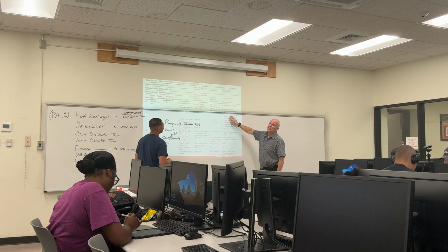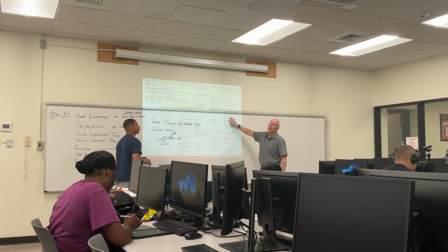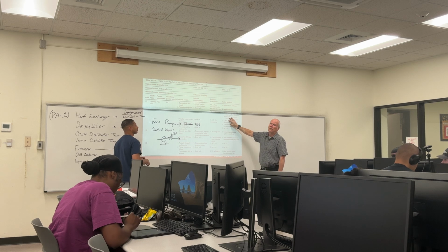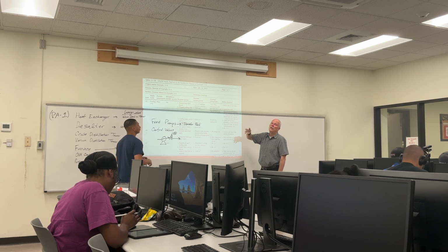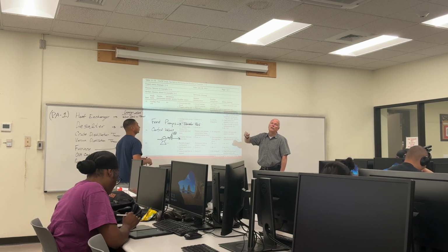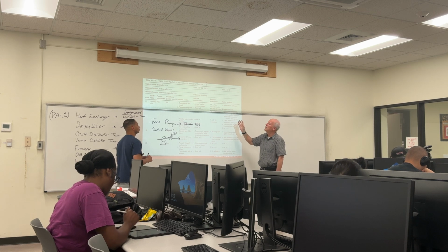Now, the action, what do they take? Well, you're not an operator, maybe you don't realize what the action is, but I think you said something about shutting a valve. So, yeah, if you shut the fuel gas valve, put that in manual, shut it, so it doesn't keep ramping up the fuel gas, that's probably a good idea, right?